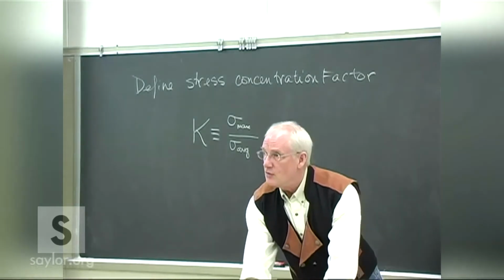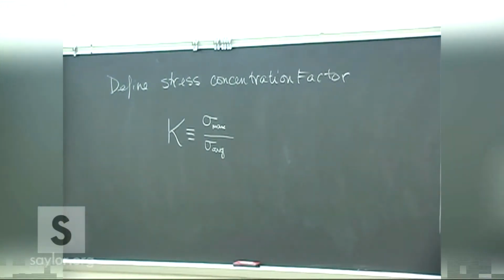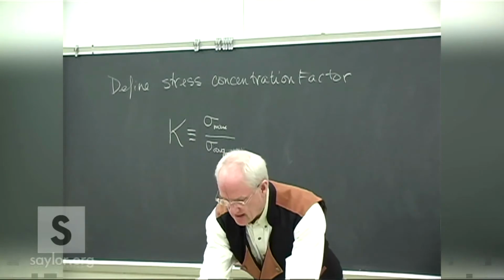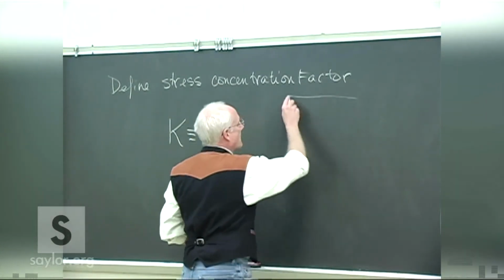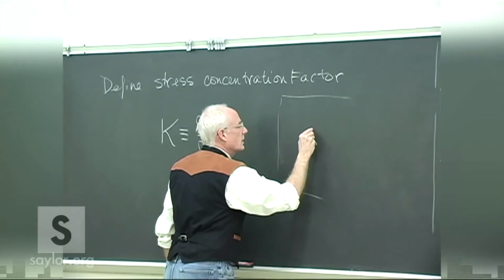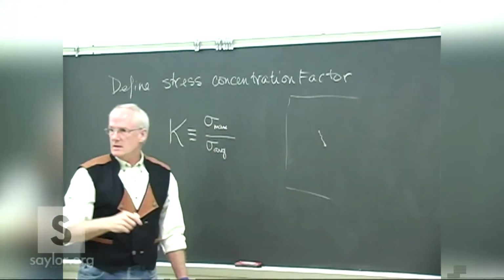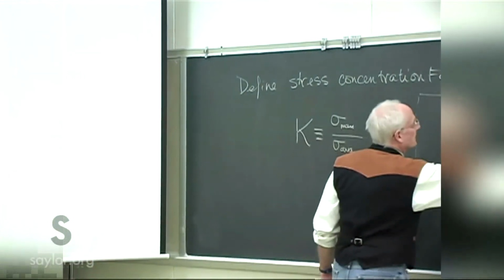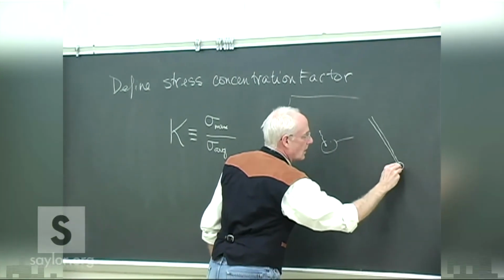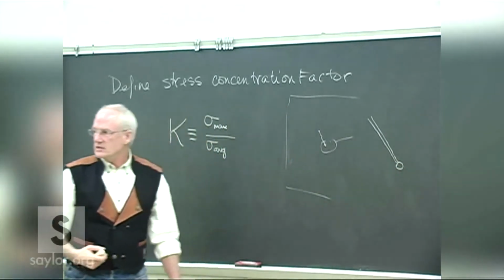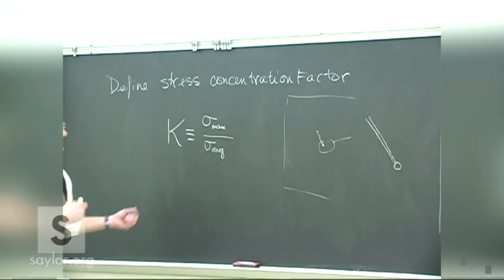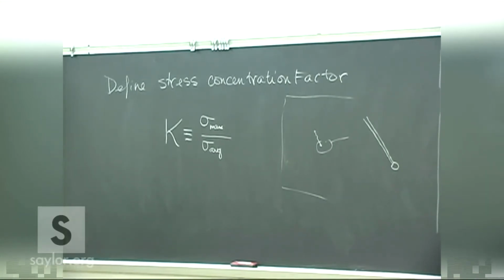If you've ever had a tarp that's gotten a tear in it, some big tarp that gets a bit of a cut or a tear, if you punch a little hole at the end of each of those, just outside of the tear, if we look at this greatly blown up, you see the tear like that, and if you put a hole there, then you're much less likely for that tear to continue to increase through the piece if this tarp is under some kind of tension, which most tarps are because you strap them down.